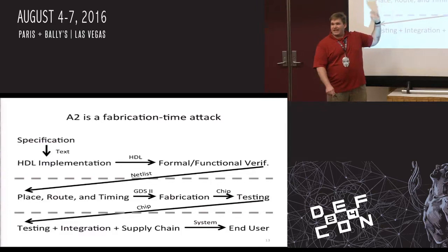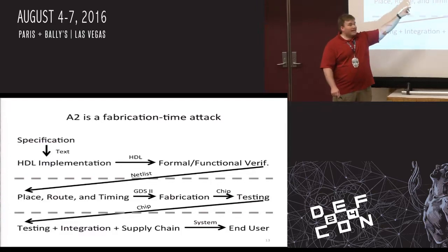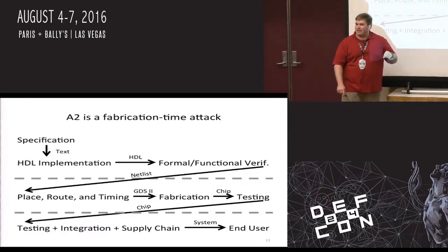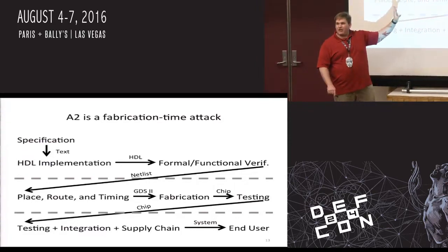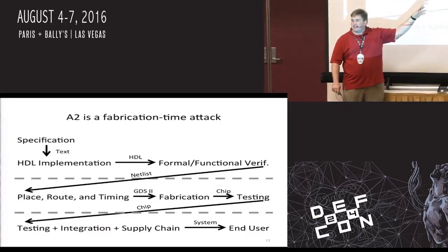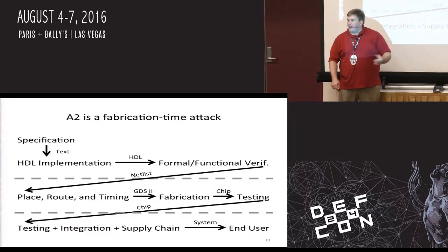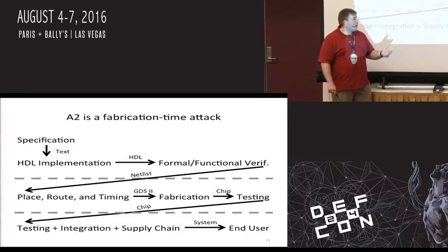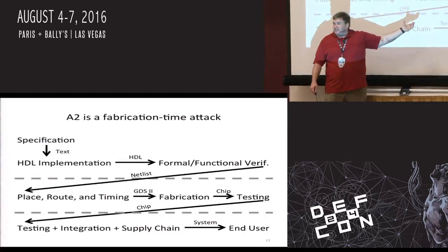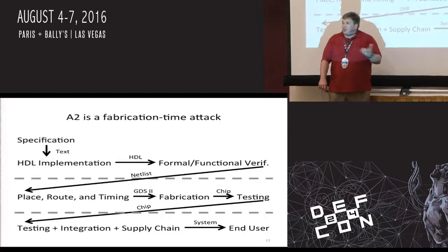So the first thing you do is take that hardware netlist, which is all the basic blocks, lay them out, connect them together using metal, and make sure everything passes timing. You create a GDS2 file, which we'll see in a second, which is basically a bunch of polygons which represent metal, wires connected together. And you go to fabricators. TSMC is a great example. Say, okay, I actually need you to build me this.